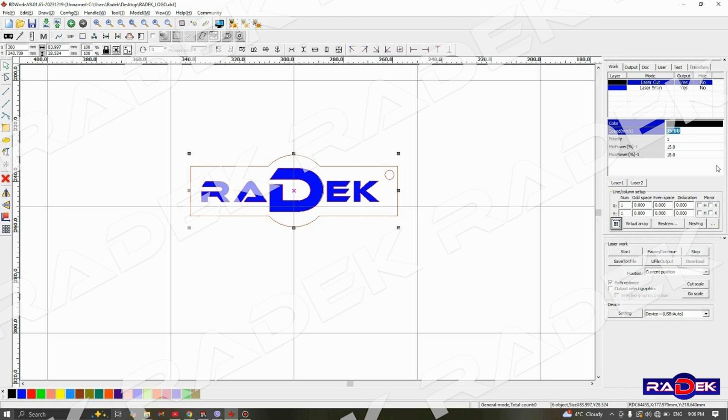A noticeable similarity in the values of the parameters is the speed required for cutting and the speed required for engraving. Usually, for cutting, the speed required is drastically smaller than the one we use when engraving. Cutting speeds are with low values such as 7 millimeters per second, 11 millimeters, and so on, and the engraving speeds are above 220, 250, and sometimes 400 millimeters per second or more. For minimum and maximum power, these values, which are already assigned, are completely acceptable.